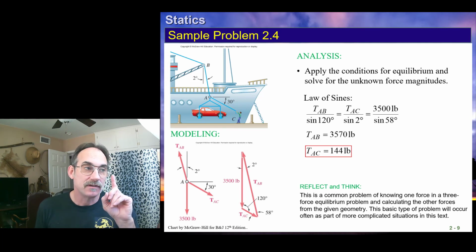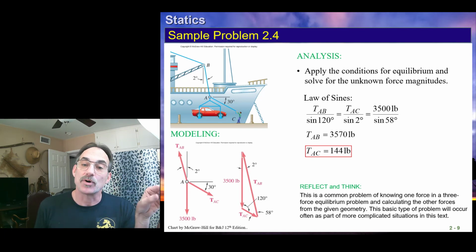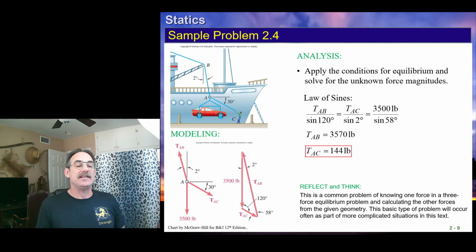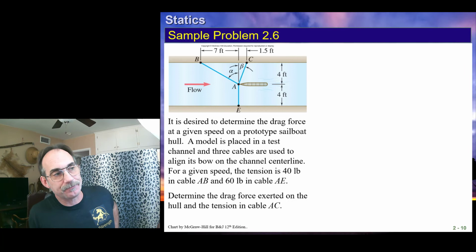Basically, it involves locating the point where the forces are concurrent. Draw all forces on the point. Impose equilibrium, which means sum your components, or draw your force triangle so those forces all close on 0, and then solve for the different pieces.